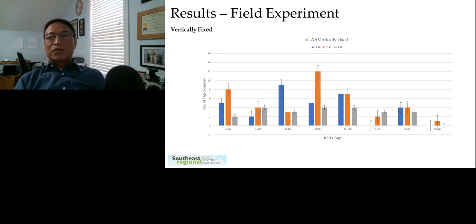These figures summarize results for the number of tags scanned while the reader is in a dynamic position based on distance and orientations. Take note that the reader here was already attached to the drone, or SUAS. Tag 2F at downward orientation shows the highest scan rate, followed by tag 59 at horizontal 90 degrees sideways left. Then tags 5A and 5B at upward and downward respectively. In addition, tag 6F at horizontal 90 degrees sideways left has the least number of scans.